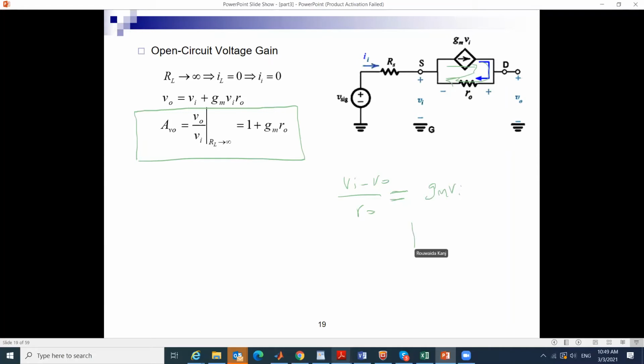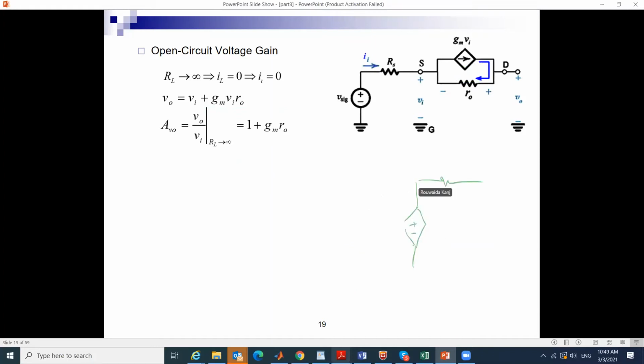Why do they teach us the open circuit voltage gain? Next time we look at the gain sheet, because when I draw this circuit, I'm going to draw it like this, and I'm going to have Rn here. Anytime I have a load resistance, I'm going to put the load across my output. So this is going to be my R load across this node here. Great. So if I have AVO times VN, and I know my RO,